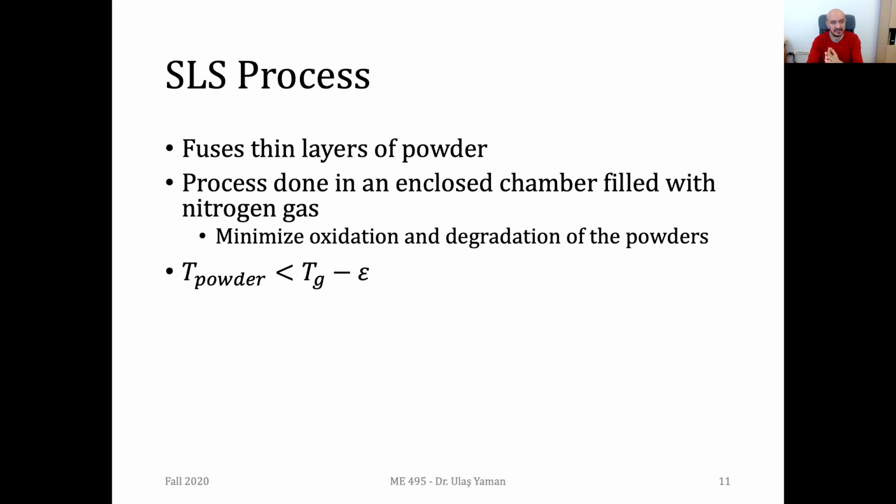So in such systems, again, we have thin layers of powder. While spreading it with the help of hoppers and, let's say, counter-rotating rollers or blades, we need to have thin layers of powders on the bed. If you have thicker ones, then it will be quite complicated and you cannot sinter them with the available laser. So that's why we need to have layers as thin as possible, which depends on the diameter of your spheres, the powders.